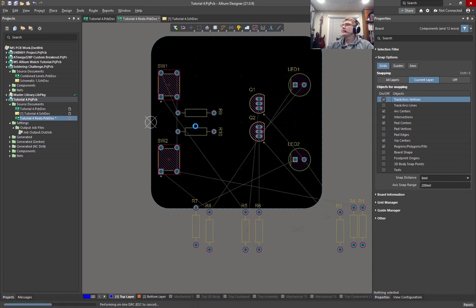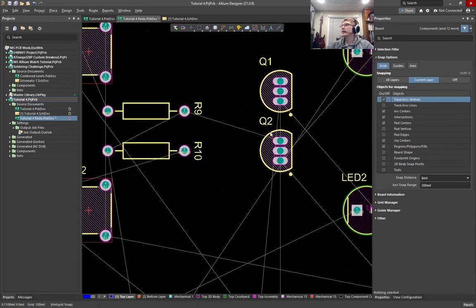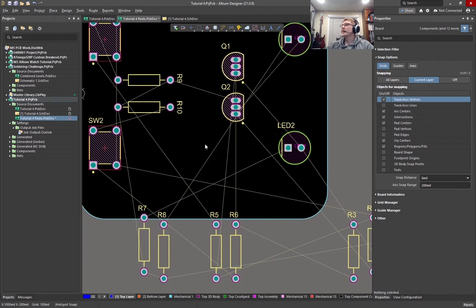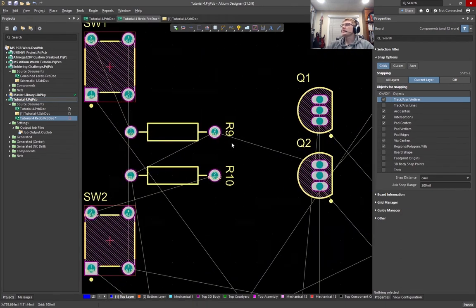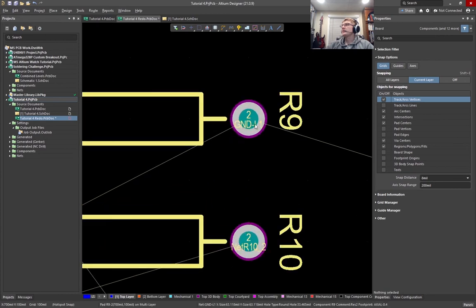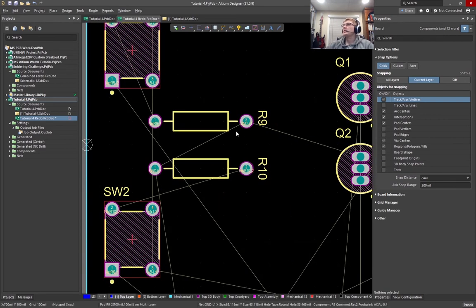So why am I doing it this way? The reason I'm doing it this way is because I have these connection lines, which we've talked about before, and I'm trying to untangle them. So there's a couple of things you want to consider. First of all, these ground connections, we're actually going to use a different method of connecting all of those. Once we're done routing every other trace, we're going to fill in all the dead space on this PCB with copper that connects to these ground planes. So we don't actually have to route them, which means we don't actually have to consider them very much when we're laying out our parts.